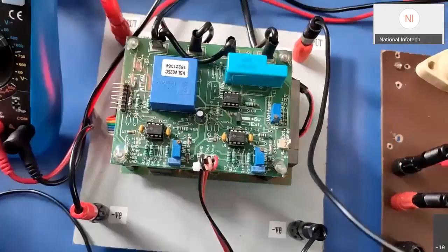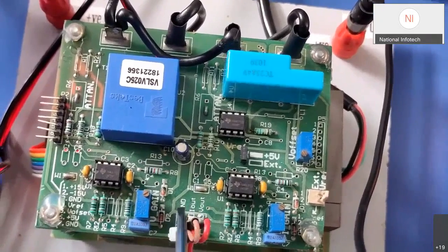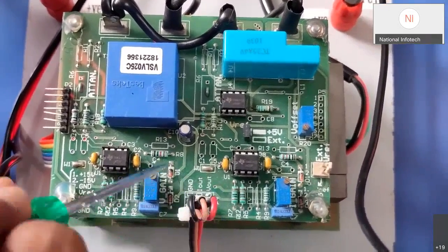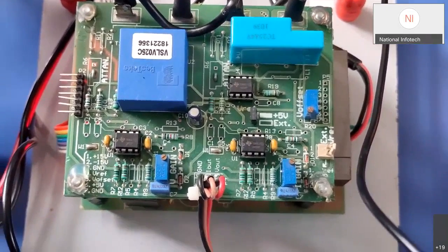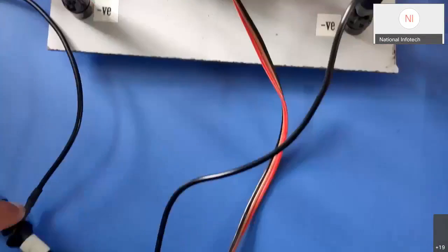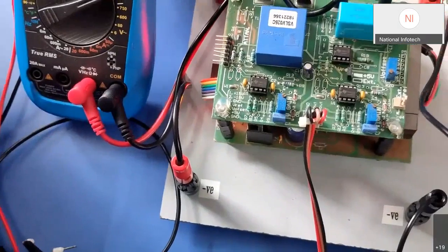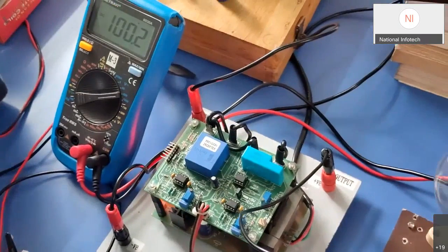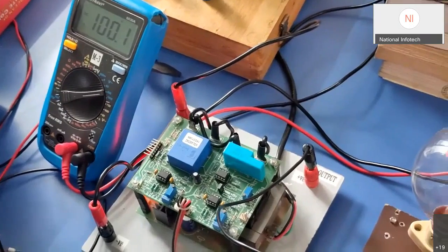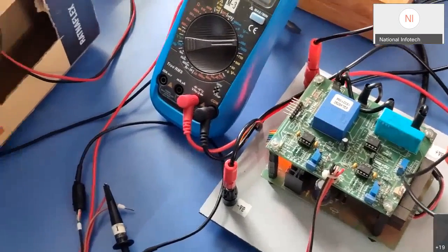This is our sensor output from where we are getting the scaled down voltage: V out, I out, and ground. From the V out we will be getting our voltage of 3 volt. We have connected the DSO probe on this red voltage out, and the black one is the ground pin. We will calibrate at 100 volt. Accordingly, we want to calibrate 200 volt to 3 volt, so at 100 volt it should be 1.5 volt.